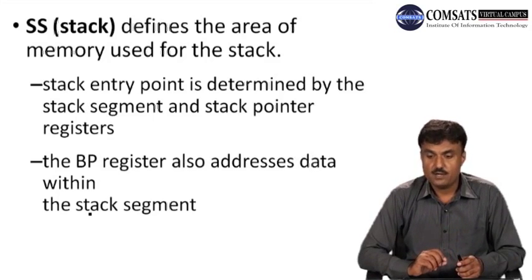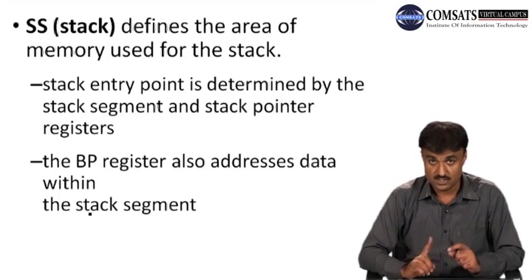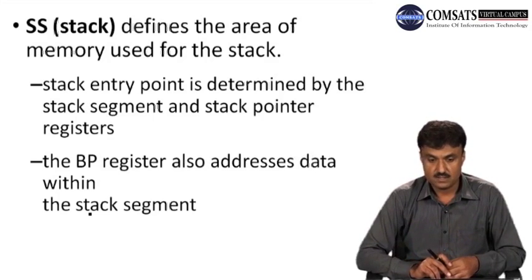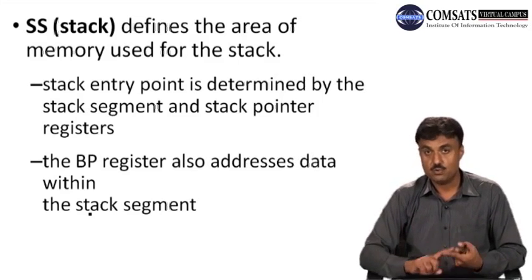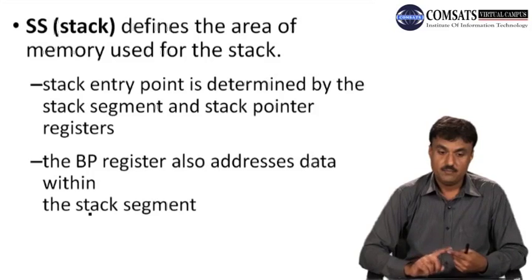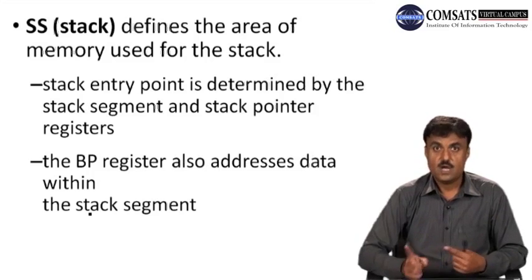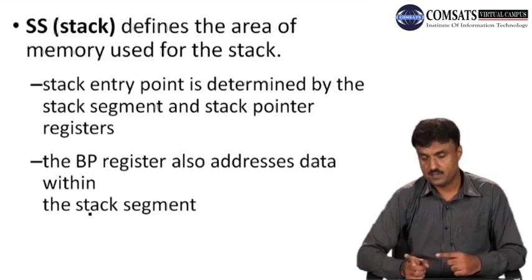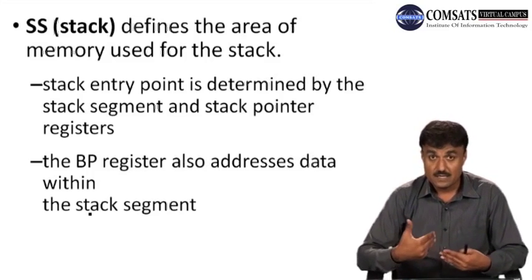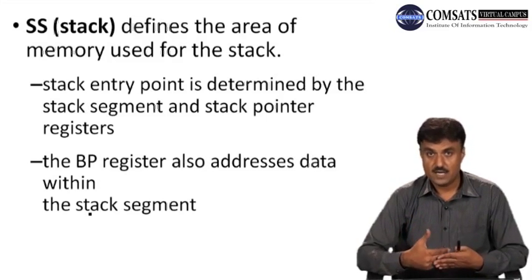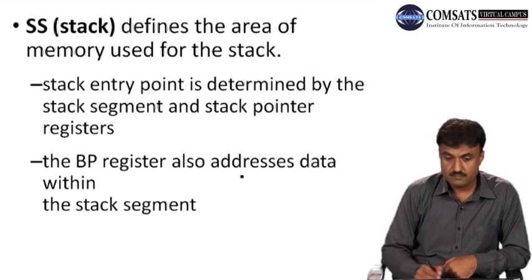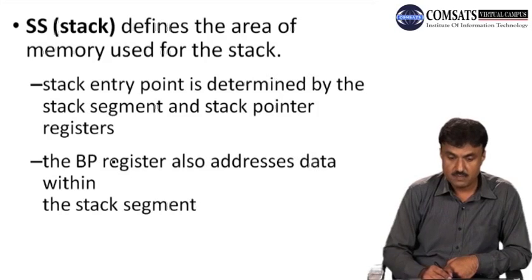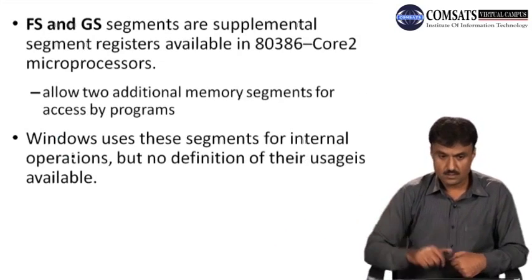So the stack entry point is determined by the stack segment and the stack pointer register. The stack segment and stack pointer register are used in combination, as I told you that the code segment, data segment, and extra segment are used with some pointer registers to access data or any address inside those segments. The base pointer register, BP, also addresses the data within the stack segment.